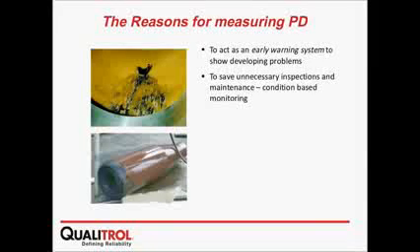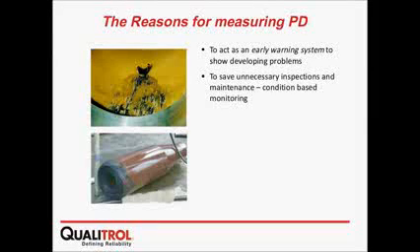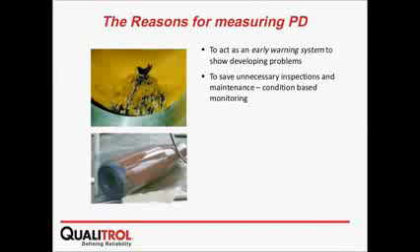And if you have a failure, even if you have your equipment under warranty, who is taking the cost of the waiting time for the parts, the field service person to do the inspection, and then the materials later on and testing? It takes a long time. It's not a simple thing to do. So with condition-based monitoring, you want to do maintenance when it's really necessary. Some maintenance is necessary every 5, every 10 years, visual inspection, but internally, you don't want to keep opening things if it's not necessary. You only open if you actually have a PD. So in the case of the GIS, you want your GIS to be PD-free.